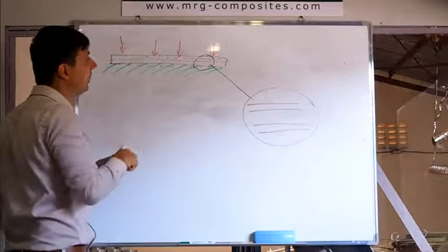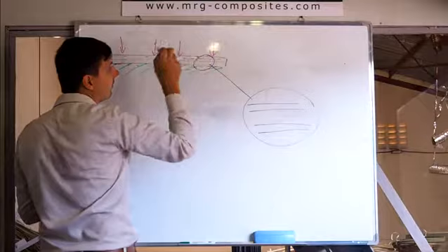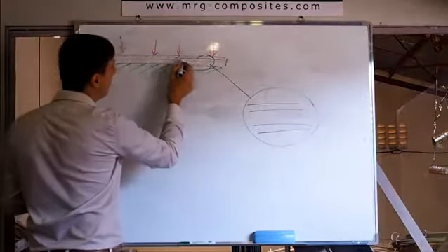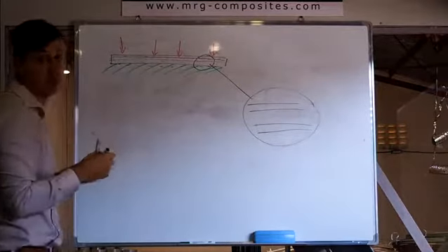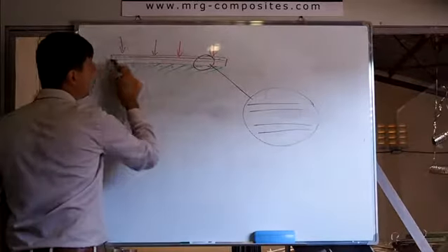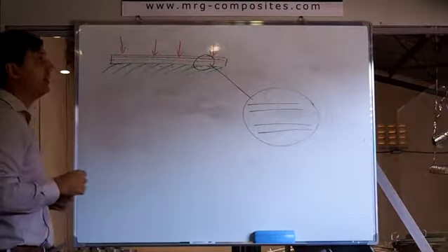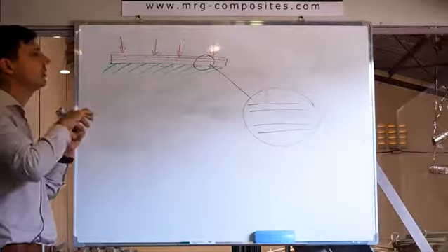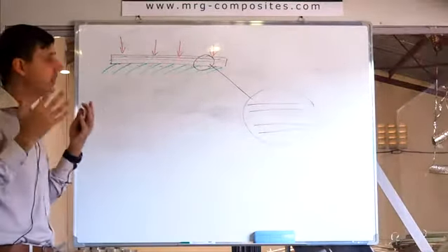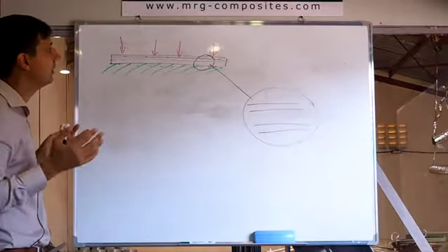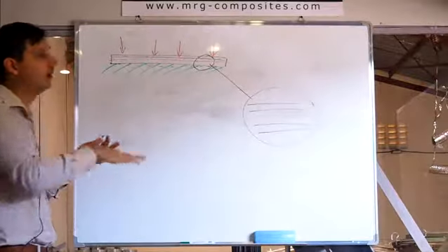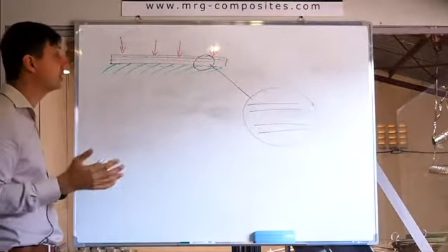And we know that if a crack appears here, it will cause rusting of all the bar along here within some time. Unfortunately, even if it is 100 meters, rust is going to be everywhere. Every engineer knows that even with a super slab, super concrete, tiny cracks are there. This is just life, okay? We can't prevent water going through concrete. Yes, we can use hydro insulation, but cracks are there, unfortunately.